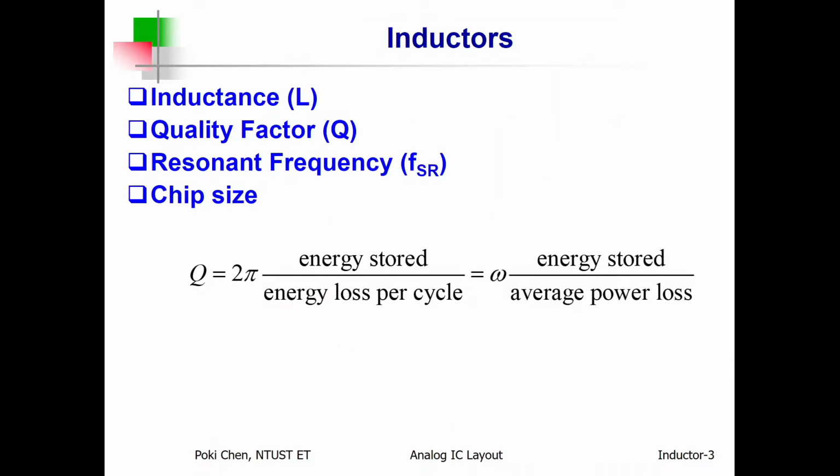So for inductor, what are the most important parameters? First of all, the inductance, and then the quality factor, the resonance frequency, and for our on-chip inductor, we pay much attention to the chip size.